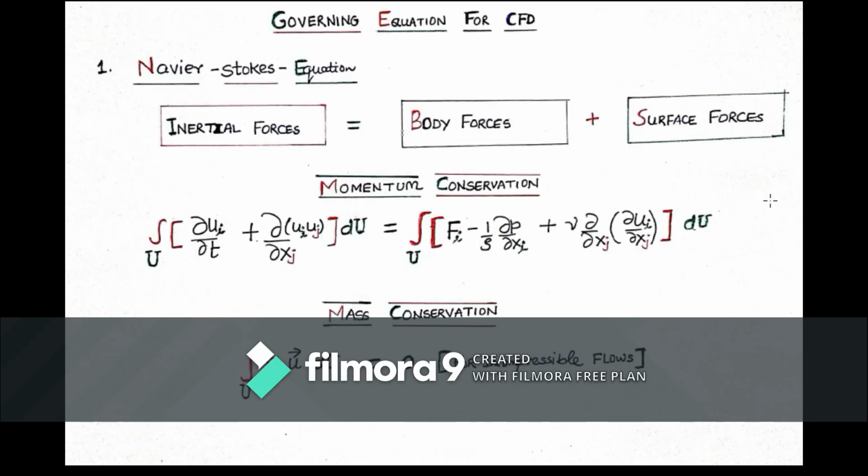Hi, so let's start our discussion of the governing equations for CFD. The main governing equations for CFD for an incompressible and isothermal case would be momentum conservation and mass conservation.